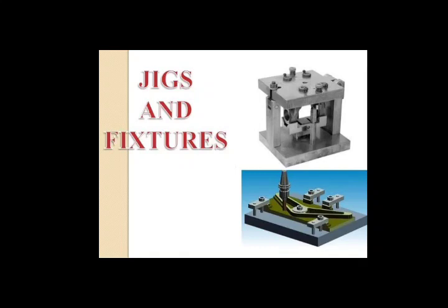Chip control: with the help of chip control technique, it is possible to reduce operator's fatigue. Manual chip removal is only suitable for lower production application. That is the point to be considered. Positioning: at this stage required positioning means can be determined. Availability of standard positioning devices can be considered while doing this.